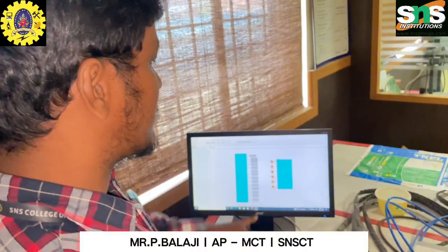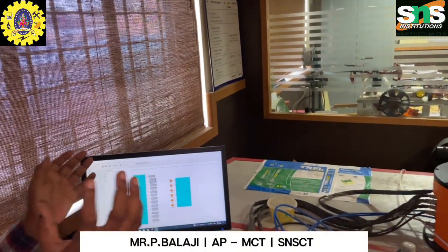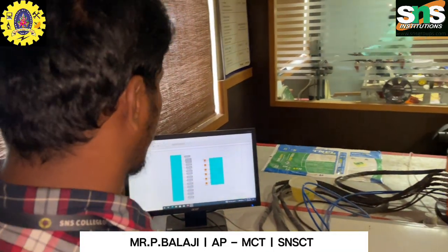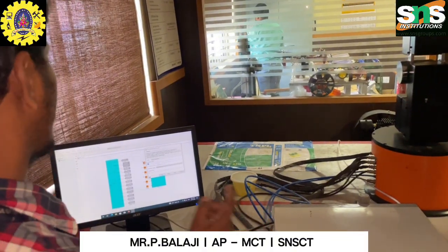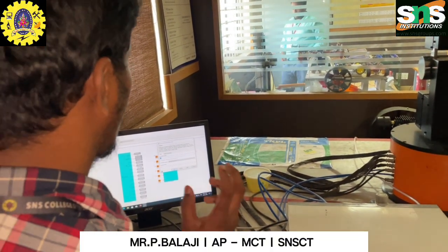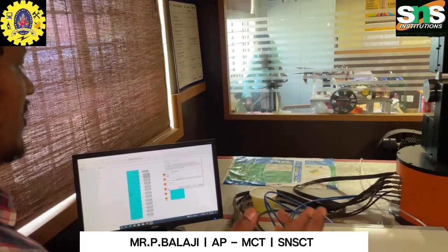The first axis is the base angle, which rotates 360 degrees. I'm going to demonstrate how it works. If you want to control any single axis, you have to choose the Robot GUI, and you have to give a value below 320 only. The 40 is the tolerance.